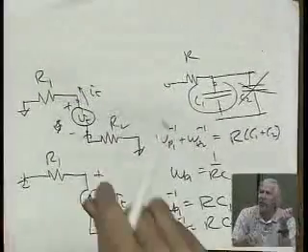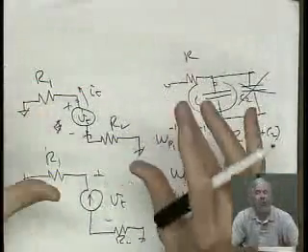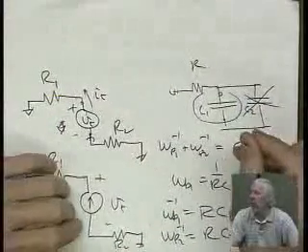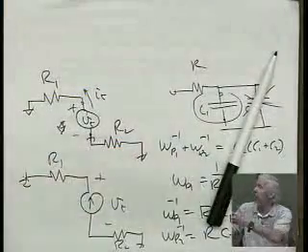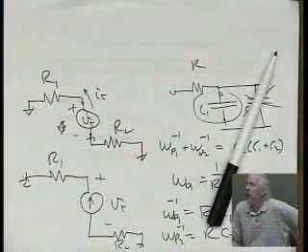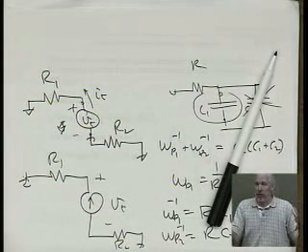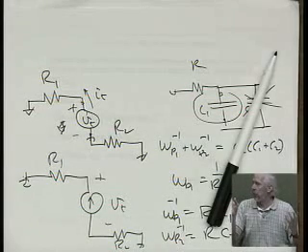That's probably, and so this is a little bit of the math behind that approach to getting an estimate of where the worst pole is, the lowest frequency pole. Makes sense? In some sense, I'm agreeing with you. If you look around, you find a bunch of them are really small, or you can look at it and see it's 1 over gm there. Just forget that one. It's not going to be the dominant pole for sure.